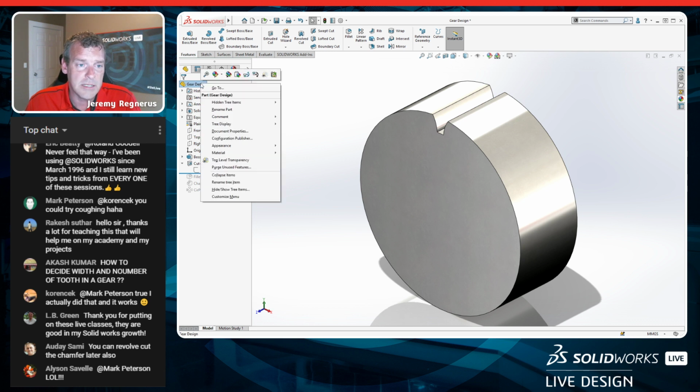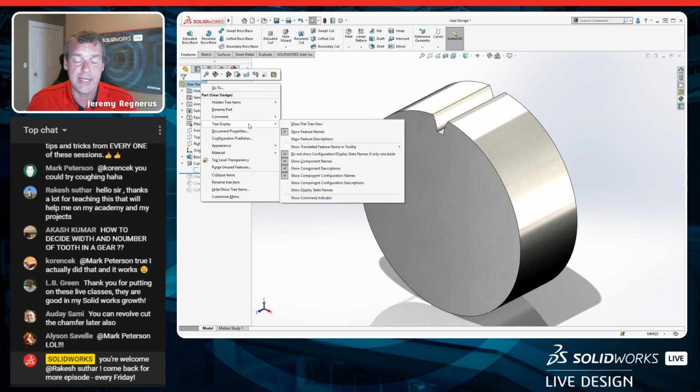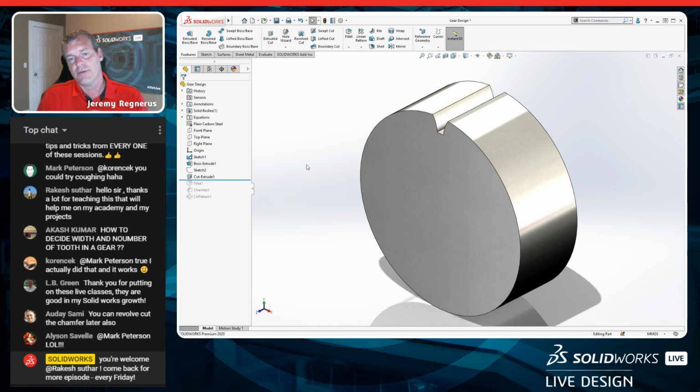You can right click on your feature manager tree and you can actually change between displaying your tree as nested items or what's called a flat tree view. And notice how the tree display has changed. It's now showing me each feature, including sketches that I've created one at a time.